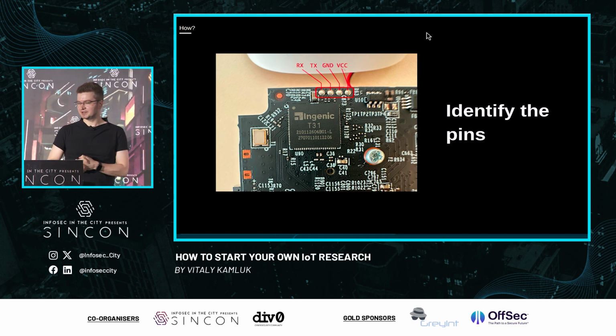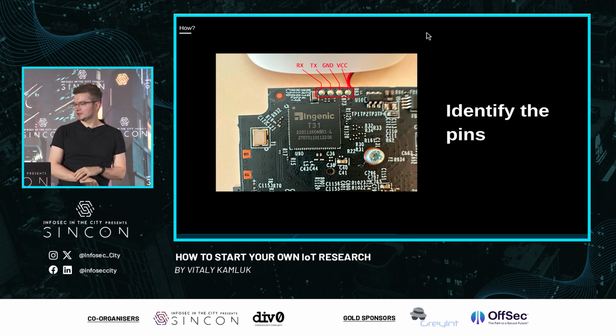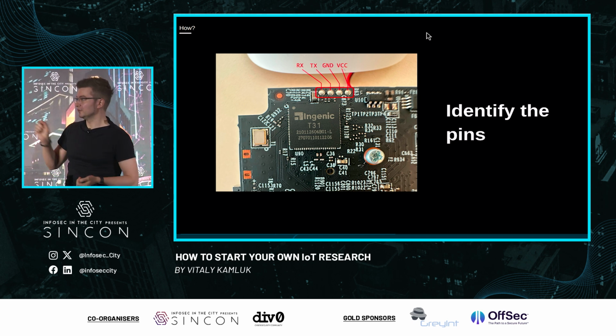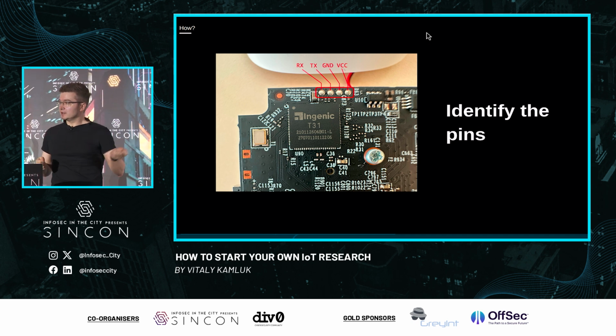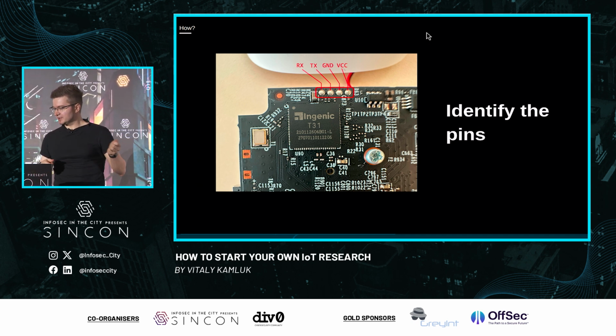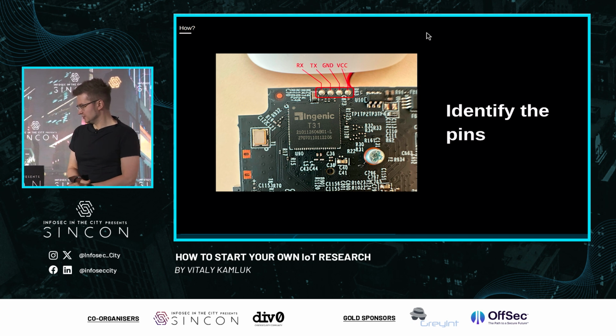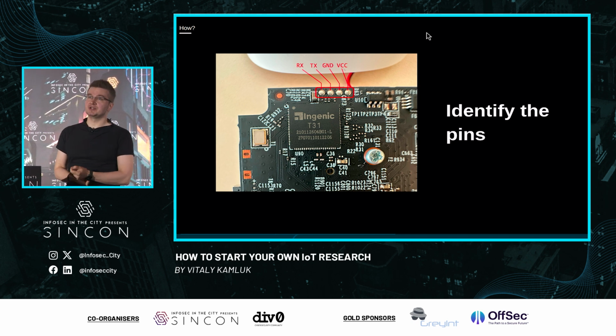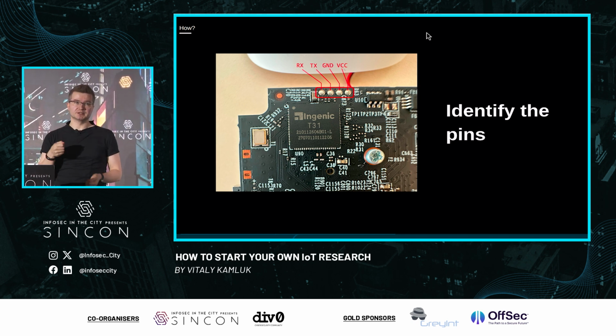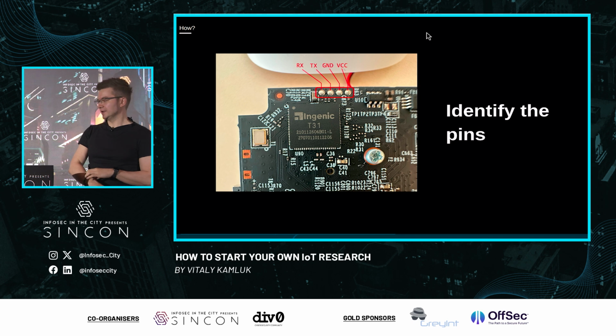And then the ground is identified by connecting to the candidate ground pin, one of the 4. And the other cable has to go from the multimeter to the ground, which is confirmed. Basically, it is on the power plug, the power barrel that you plug the cable in. There's a ground on the outside.